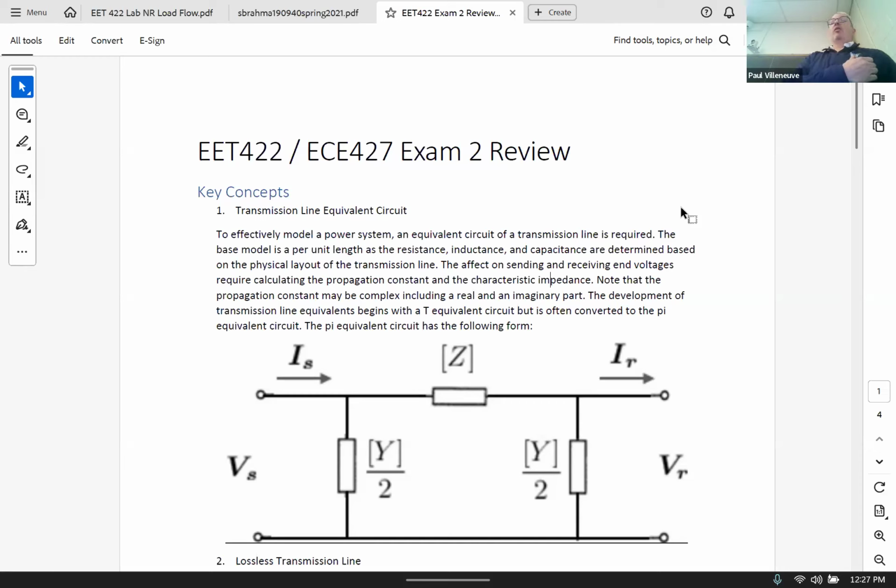You can check your Jacobians and your power balance equations, because one is prone to error in making those. So the meticulousness of being able to write those is pretty important. What has helped me figure out how to write those equations is really just lots of paper.